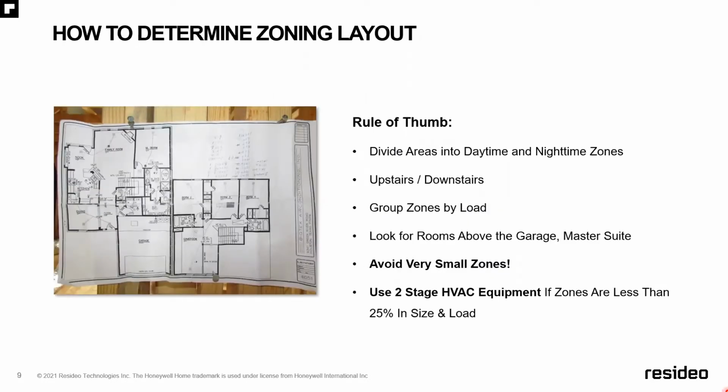Okay, so when you're deciding where to place these particular thermostats, it's important to keep a number of factors in mind. You need to think about what's going on during the daytime, what's going on nighttime-wise when it comes to the zones, what's upstairs and what's downstairs, and what's going on as far as the loads. We've got to pay some attention to which way the house is facing when it comes to northwest, whether it has a southern exposure with a lot of sunlit glass, things like that.